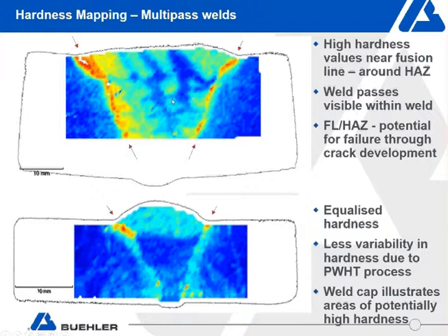And for this top weld, what is of concern is near the fusion line, the heat map shows it's considerably harder compared to the base metals on either side of the weld. And this potentially is where we say failure may occur during service along the fusion line into the HAZ because of this high hardness, or what we consider high residual stresses.